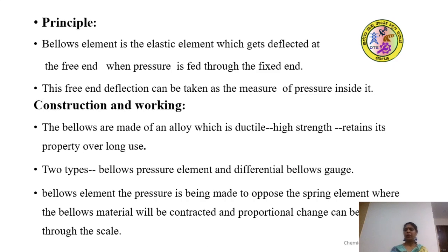So, on application of the pressure, the bellows moves and the movement of the bellows is opposed by the spring element. On the application of the pressure, the bellows will be contracted, and the contraction is proportional to the change in the pressure, which can be indicated by the movement of the pointer onto the scale.